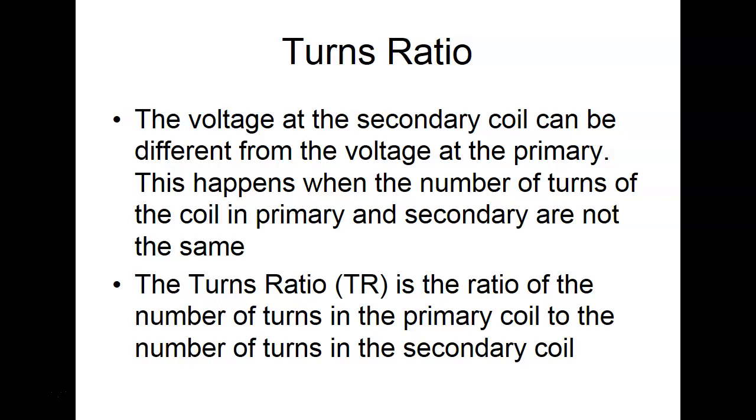This is why on industrial transformers, the terminals on the primary are labeled with X's. I mean on the secondary, they don't use S. And on a step down, I'm sorry, the low voltage side is labeled with X's, and the high voltage side is labeled with H's. This is the way the terminals will be labeled.